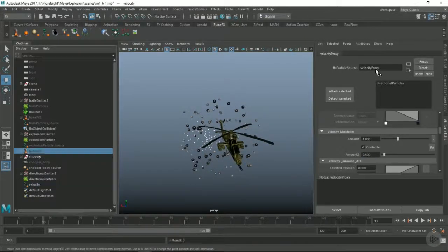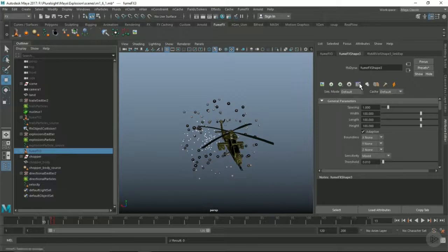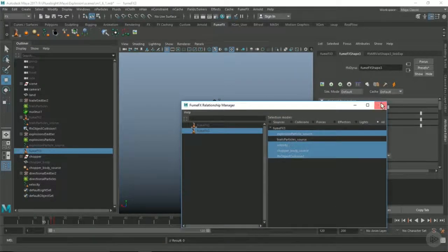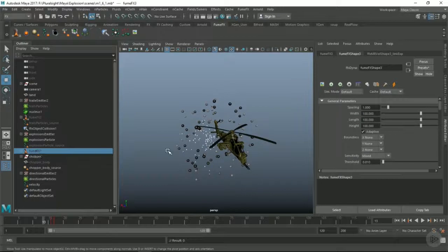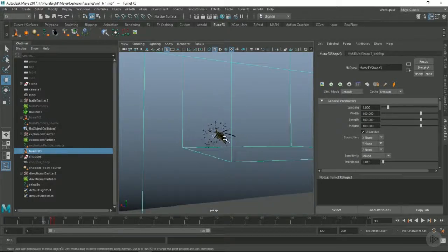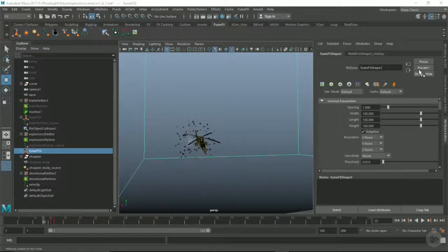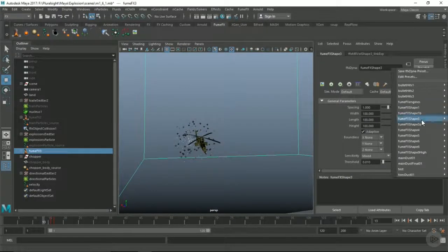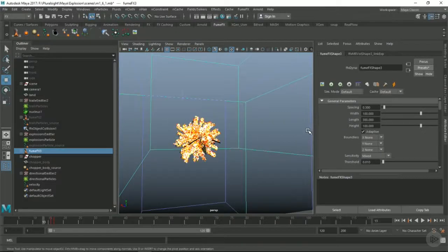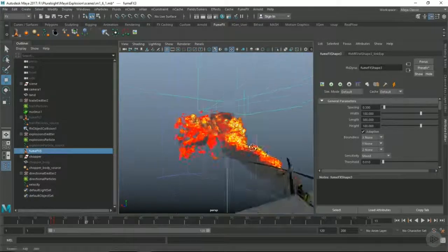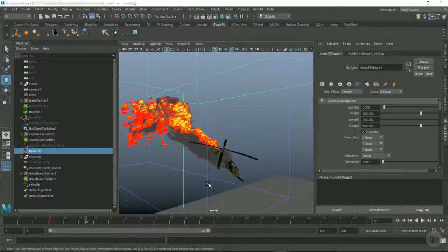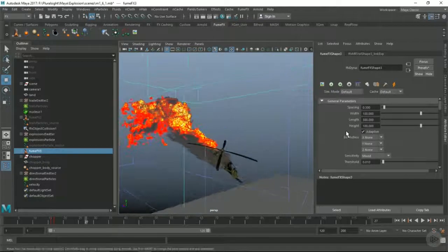And now let's just make some final adjustments to our fluid itself. So I'm going to drop the spacing to 0.2. Let's set the end frame to 150. Even though we're emitting to 60 or 65, we just want to keep the simulation going until it dies out, so it's still kind of in the frame.